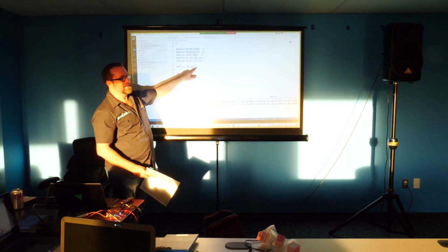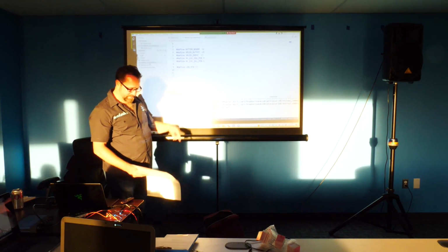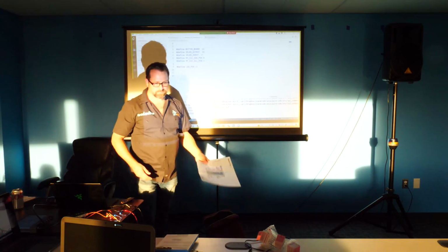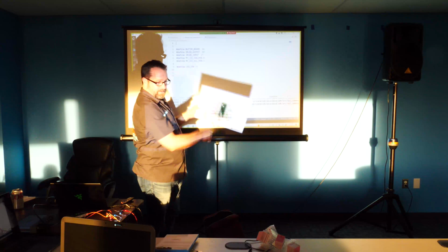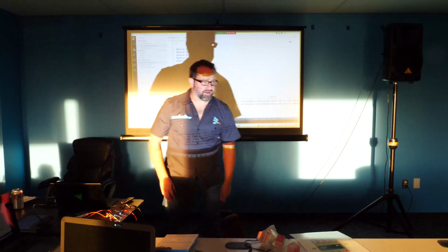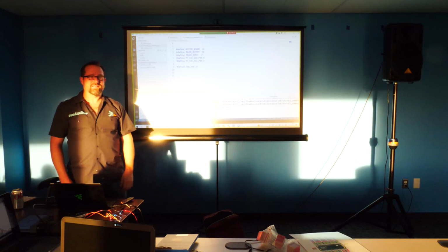This is actually the LED on the board. That's always 25 on the Raspberry Pi Pico, which it actually shows on here. One of the things that's nice about the Pico is that the pins are very flexible.